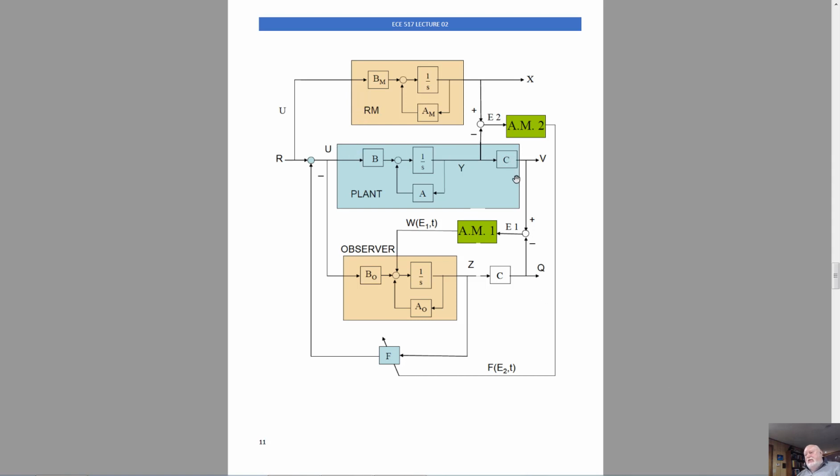But then there is another model reference problem. The control plant is a reference model in the adaptive observer system. Now, the control plant is a real physical system, but we use it as a reference model to adjust the observer. An observer is a module, a simulation module in a flight control computer probably. So we have two different model reference systems, two different adaptation mechanisms, two different errors extracted.